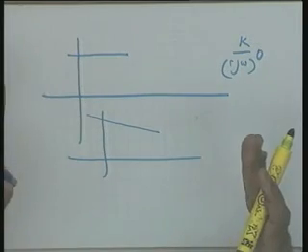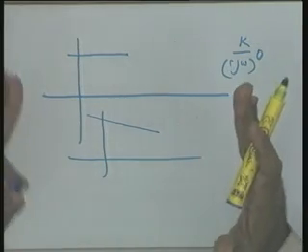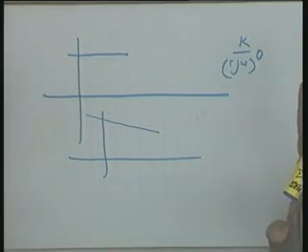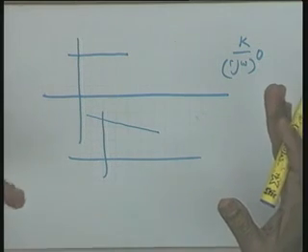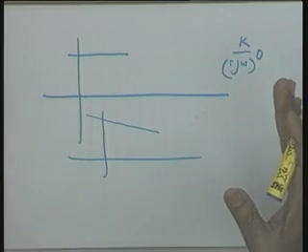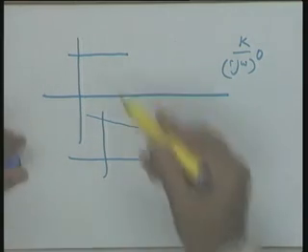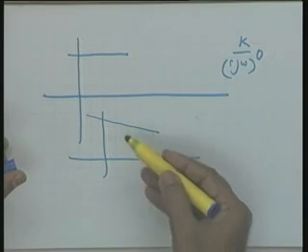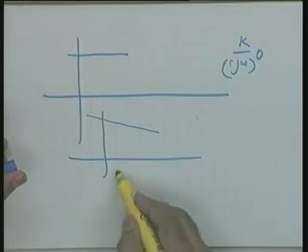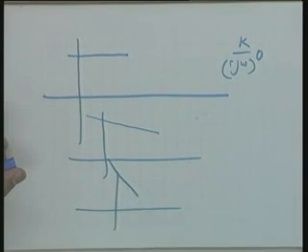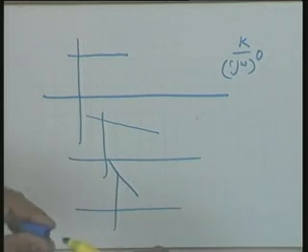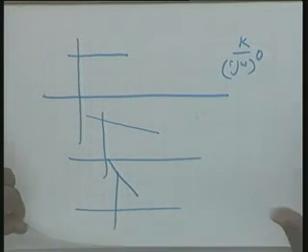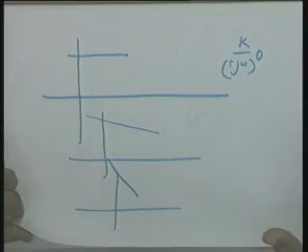So, interestingly, the Bode plot, just the very sight of the plot, the magnitude side of it, tells you whether you are handling a type 0 system, a type 1 system or a type 2 system. A 0 dB per decade line, a minus 20 dB per decade line or a minus 40 dB per decade line in the low frequency region tells us which type of system is under consideration. Maybe the transfer function model is not given to you, but still you can tell which type of system you are analyzing.